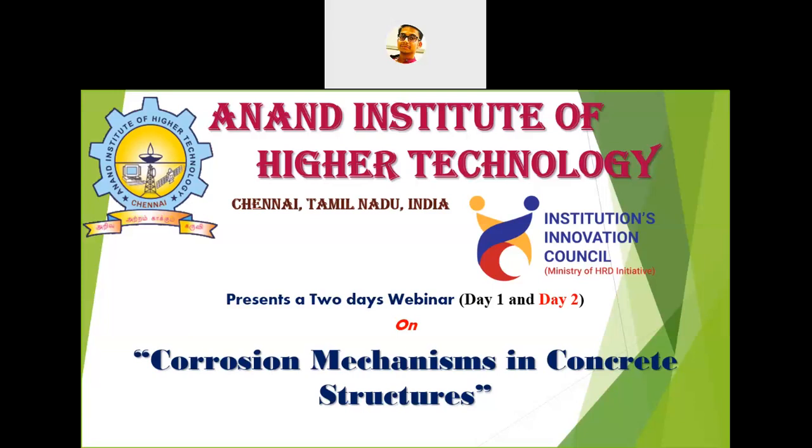And after that, the two prime reasons of corrosion: one is carbonation induced corrosion, which happens due to the induction of carbon dioxide gas into the concrete system, and the other is chloride induced corrosion. So today we will see the rest of the topics in the second day.